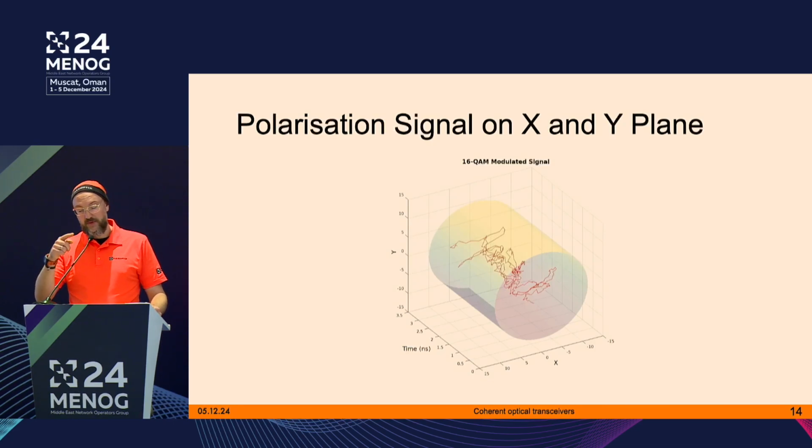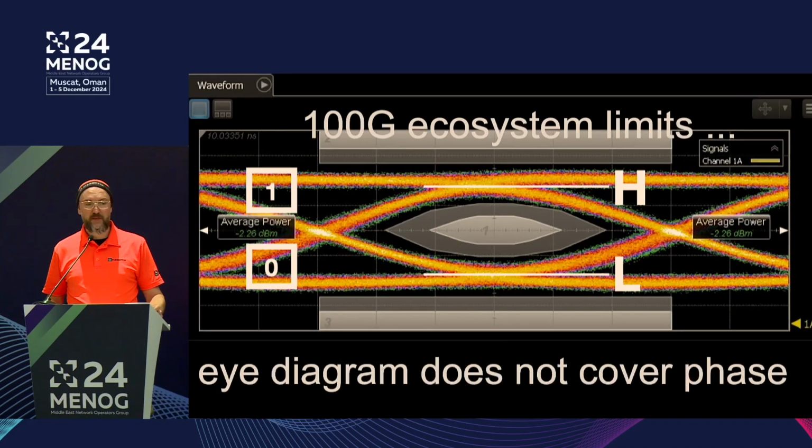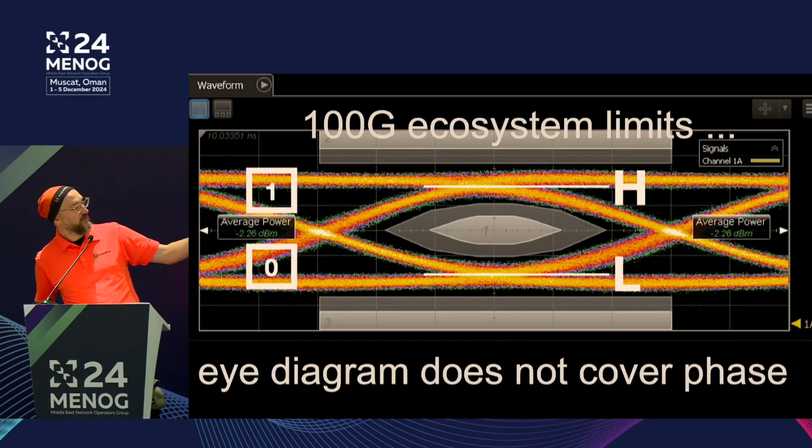Having said that, at the beginning with the 16 QAM, I need to do a step back. So far, typically when you want to look at an optical signal, and when we are talking about direct detection transceivers, an eye diagram is typically used to measure the quality of your link actually. So an eye diagram, as you can see, you see the curves up and down going.